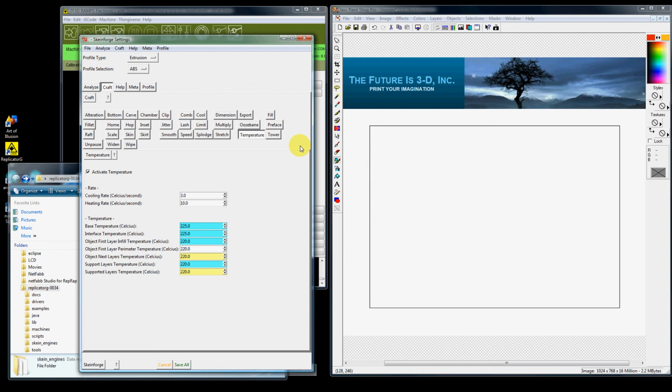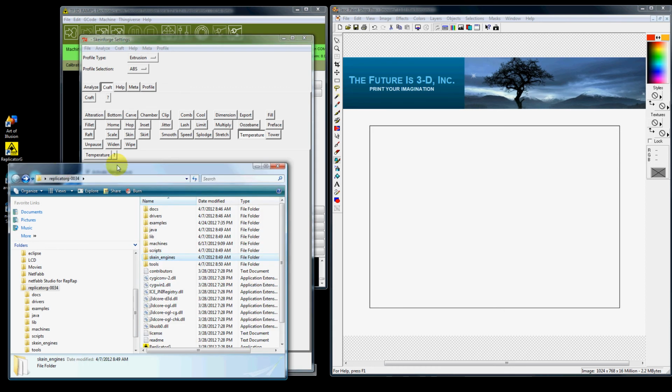My name is Jeff Christiana and this is video number 30 of the Skeinforge 47 video training series on how to use temperature. Under Skeinforge, your temperature tab, used by default in our profiles, we have activate temperature. If you did not activate this temperature, it would use the default setting in your start.g code.